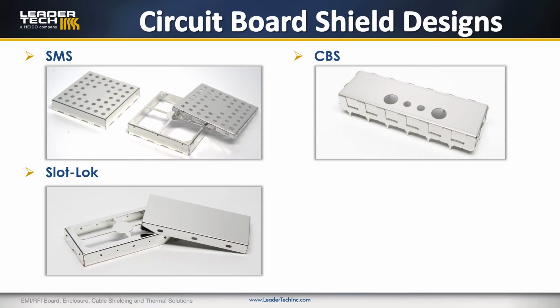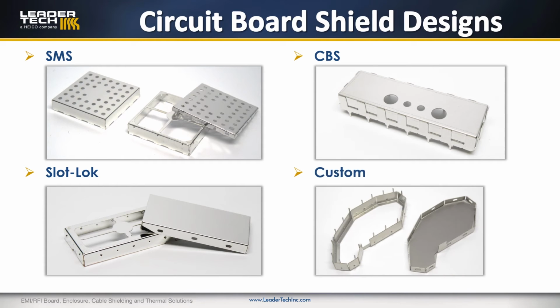The slot lock shield is a fully customizable type of shield. So when you can't make a standard product fit on your board, we can make this type of customizable shield that will fit to what you've already designed your board to be. And then this shield is an example of a fully customized product. Something like this is when EMI is an afterthought. And obviously something like this would be by far the most expensive type of shield.